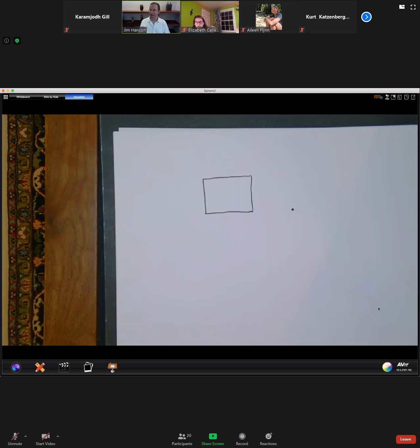Any thoughts on that one? Is it possible to do that? Can we use the M&N chart to get stress at that location? Would you split it up like how you did for the other one that was off center, and then use triangles to figure out at what depth it would hit the corners of those split up rectangles?